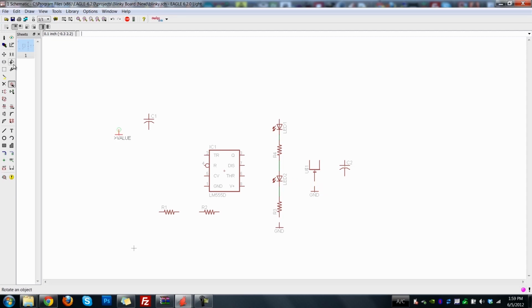So what we're doing, just like when you would draw a schematic by hand, you can have two pieces that aren't actually connected to each other, but are still electrically connected. So we'll connect ground to here, and ground to here. Now, even though these two things aren't shown with a wire connecting them in the schematic, they will still be connected when we go into the board layout view. And that's all that we really care about. And it'll just help keep things a little bit neater.